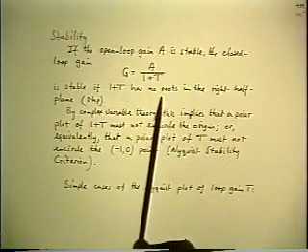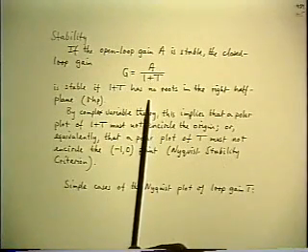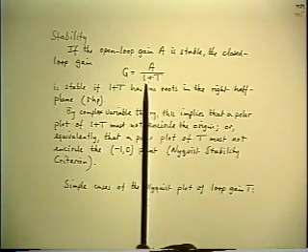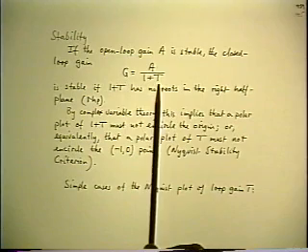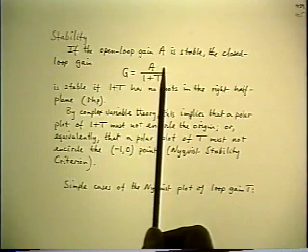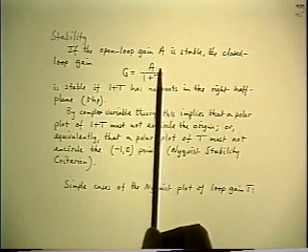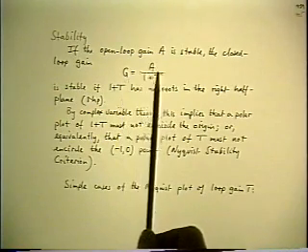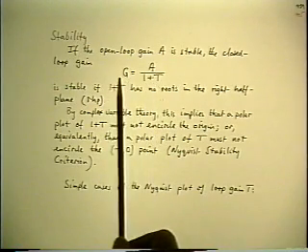Now let's relate that to a feedback system. The closed loop gain can be written as the open loop gain divided by 1 plus T. The open loop gain itself can be written in factored pole zero form. Notice that the poles of A are also poles of G, because anything in the denominator of A is also in the denominator of G.